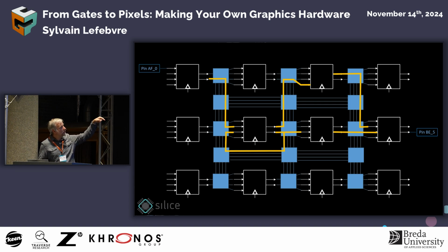It also takes time to go through the switch boxes, so the delays are much bigger than what you would get on an ASIC. It's also taking a lot more space for what it does because of all the configuration and all the memory that is inside for enabling this configuration.